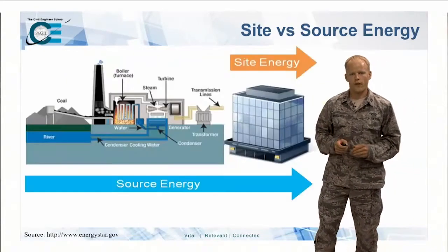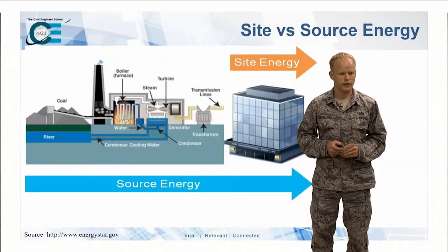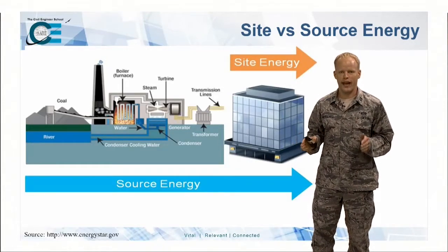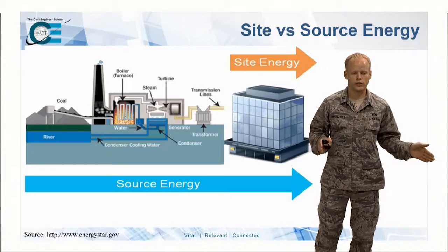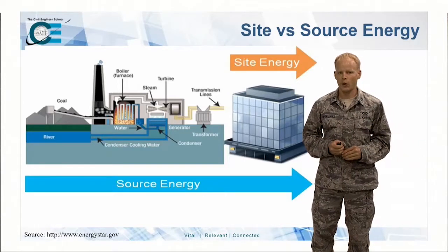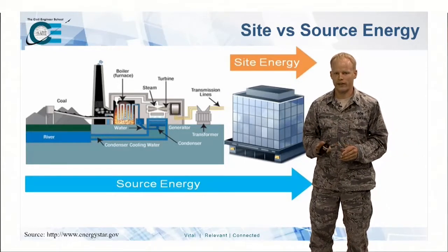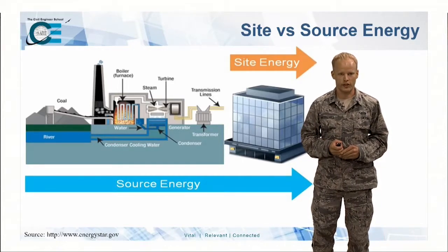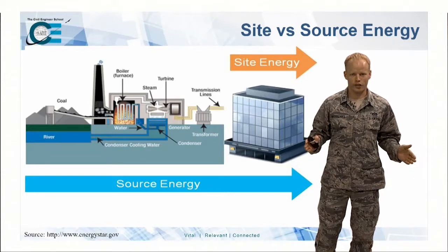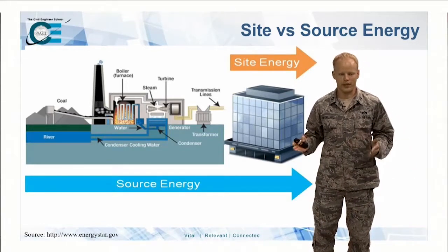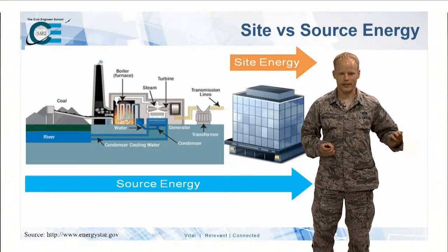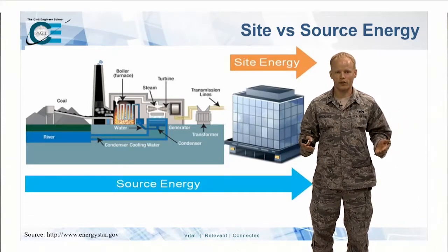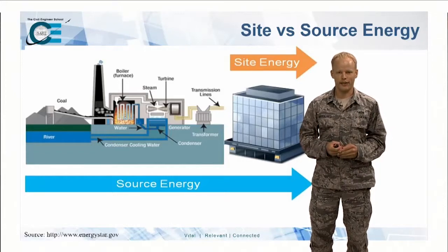So if we're talking about site versus source energy, if we were to reduce the amount of energy we use at our site, we will reduce our source energy by 2/3. The factor that we say is source energy is about 3 times greater than your site energy. So we save a whole lot of energy over this. But in reality, we really only care about site energy. The rest of it is caring about the planet, which some of us like to do, but us in the Air Force, we just care about saving energy at our location.